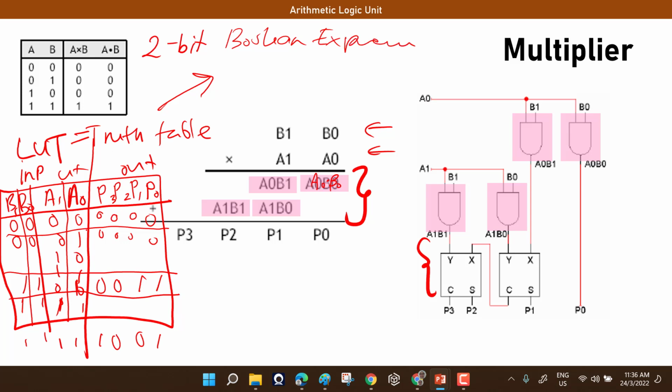How do you get the Boolean expression from the truth table? What do you need to do normally? Okay, ma'am, maths. Need is not the right word, you can. Why is need not the right word? It is not compulsory to do a K-map. If you don't do a K-map, what you would do is extract the ones from this output, like the one we saw in our class on PAL and PLA. You can extract that and later use Boolean axioms to get the simplified equation. Why do we need a simplified equation? Because we want to use fewer gates and so on.